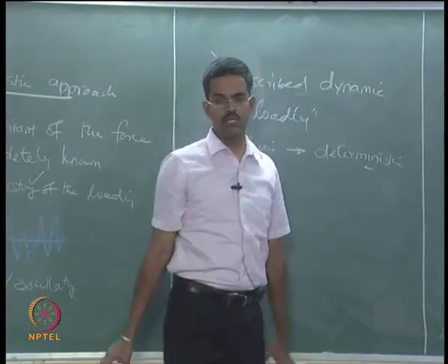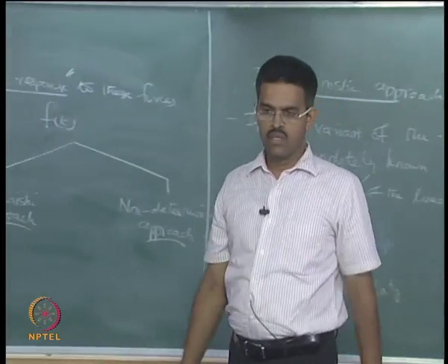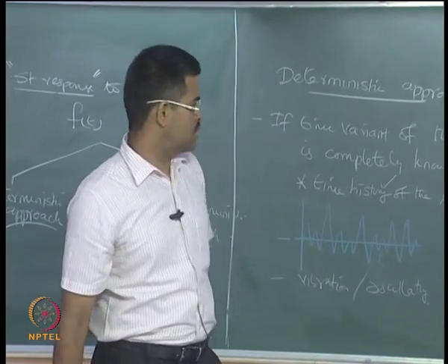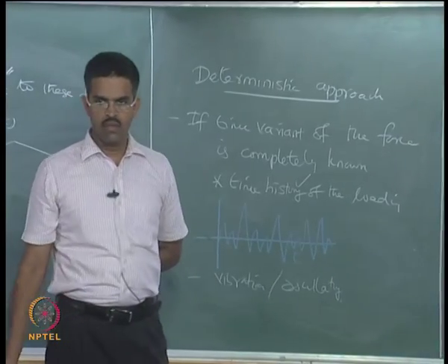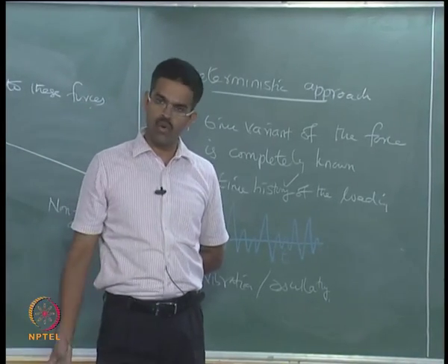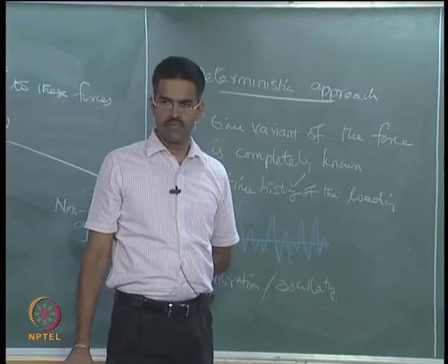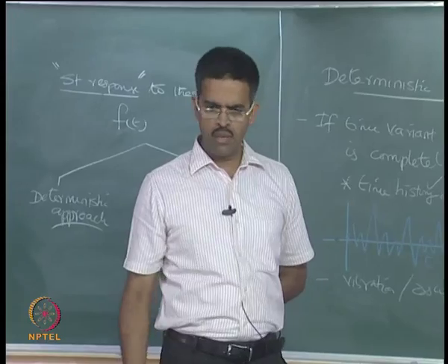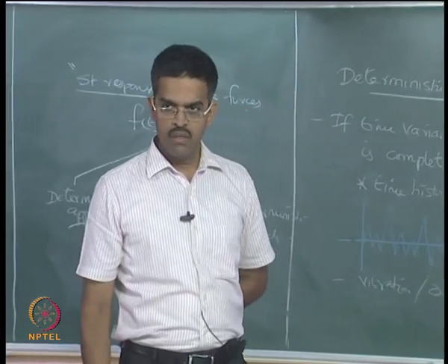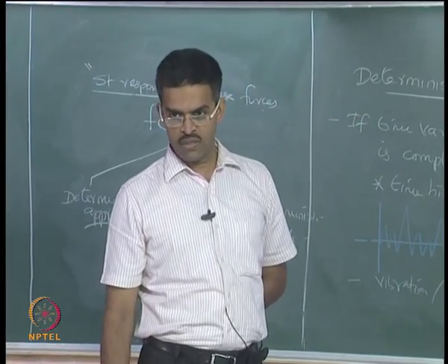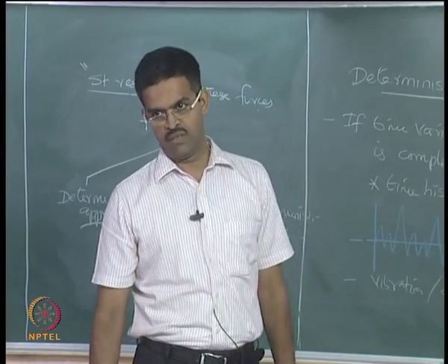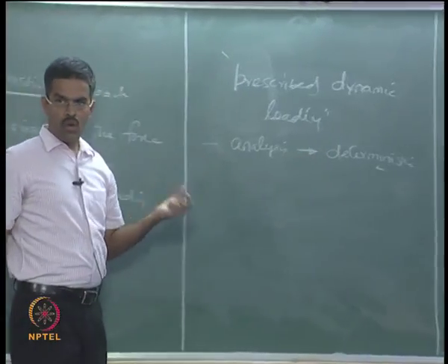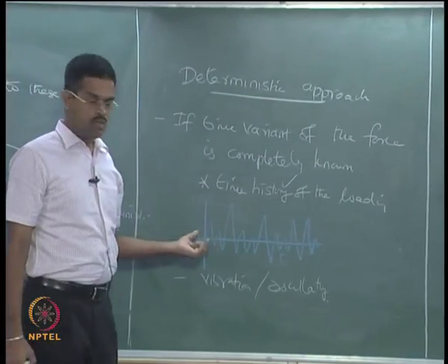In general terms, deterministic means known, non-deterministic means unknown. In general terms, for structures, determinate means the reactions of the structural support system are known to me using the standard set of equilibrium equations. Indeterminate means some of them are not known to me, and with the help of standard equations I have to solve them using some techniques. So, deterministic is related to knowledge of the time history.